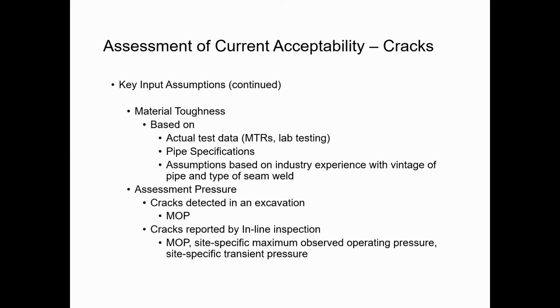And when we talk about cost, it's not that the decisions are based solely on cost. I think just about every operating company will make the money available to address anomalies that need to be addressed. So it's our job as the integrity engineers to help senior management make those decisions. If you have very conservative criteria, very conservative assessment approaches, you make a lot of anomalies appear to require remediation that, if you were to look a little closer, might not. And so that's the idea of providing a means of prioritizing the excavations for you.